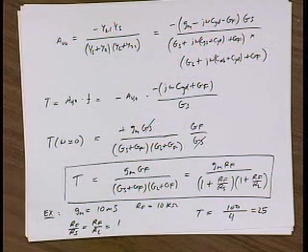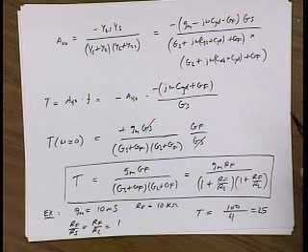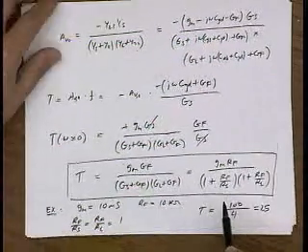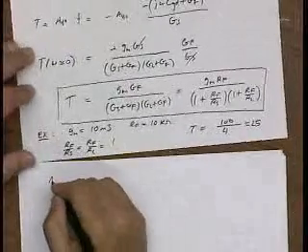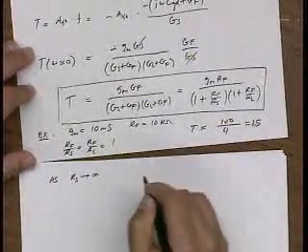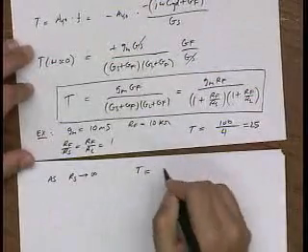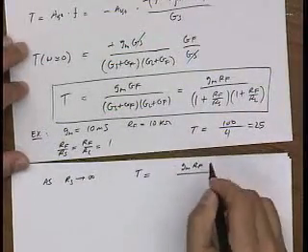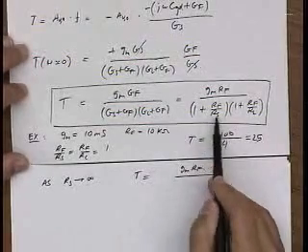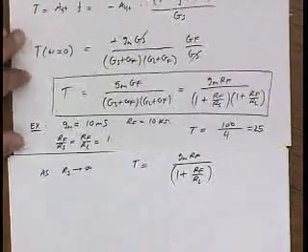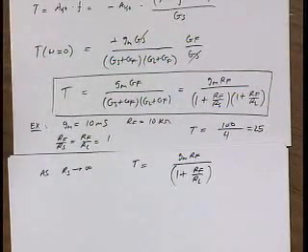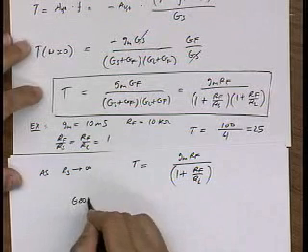Now let's go back to Daybell's question. Daybell was saying, well, you'd calculate the voltage gain, but really you should drive this with a current source. And in fact, the equation tells us that. Look at the limit as RS goes to infinity. In other words, that means a current drive. Then the low frequency loop gain just becomes GM RF, independent of the source resistance. This term goes away. Times 1 over 1 plus RF over RL.